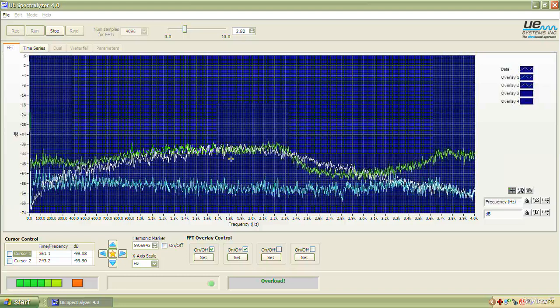So overlay number 1, the reddish orange color, is Corona. The green is tracking, still with some harmonics left at the very beginning at the 60 Hertz, and then tracking in this stage here, and it looks nothing like the Corona. So, is it tracking? Is it arcing? What's it doing? This is how we analyze it. We compare. Okay?